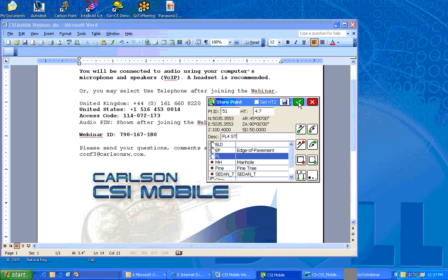And what I wanted to point out was this business of the height. It's been at a target height of 4.7. If I say, give me some other options, it brings up every other target height you've used previously. And you can say, well, just switch me one time only to a booted pole at 8.2. Now take the shot and start my new fence line